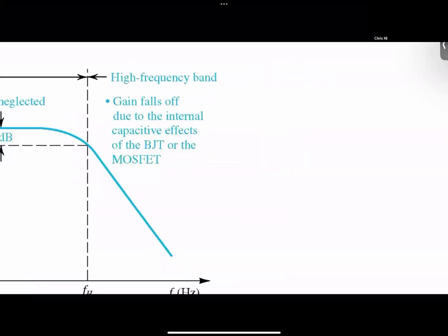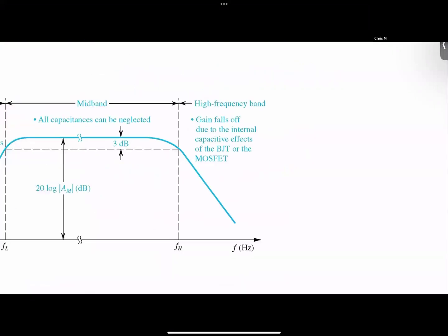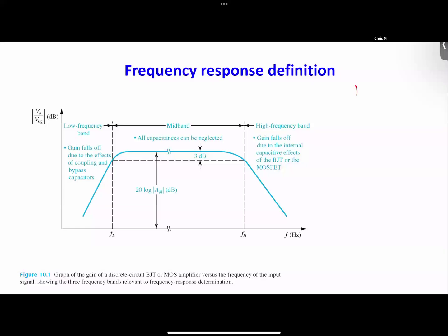Like, why is this 1/√2? Because if you look at the equation that we have, 1 plus j omega RC. Just take this example. And our A will become 1 over the square root of 1 plus (omega RC) squared.